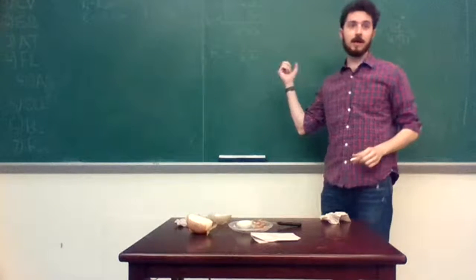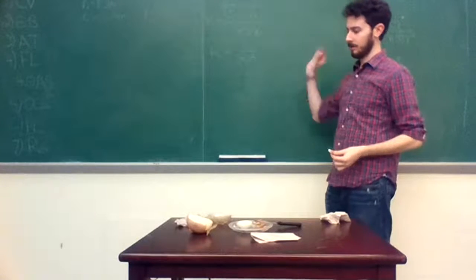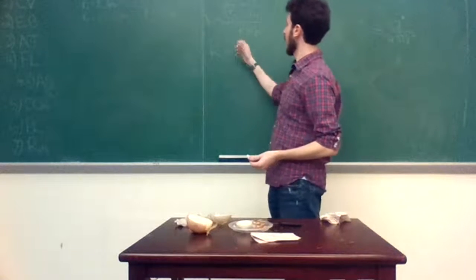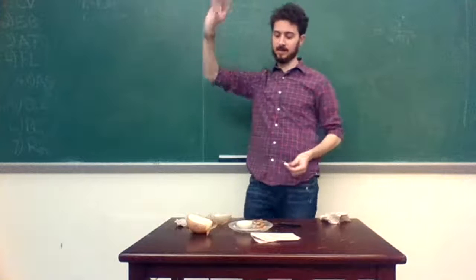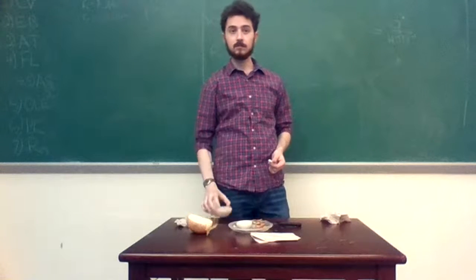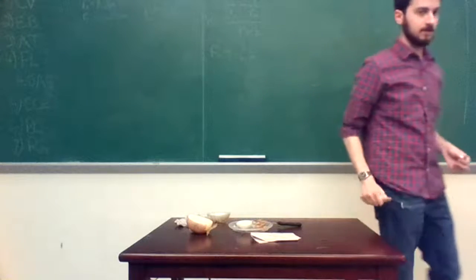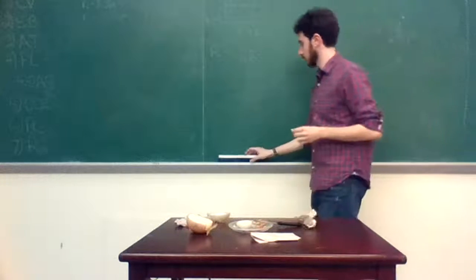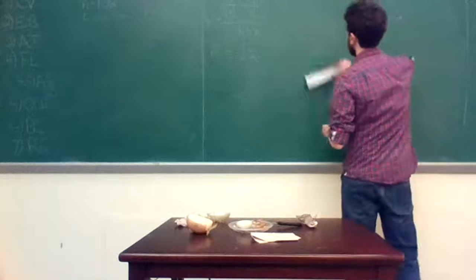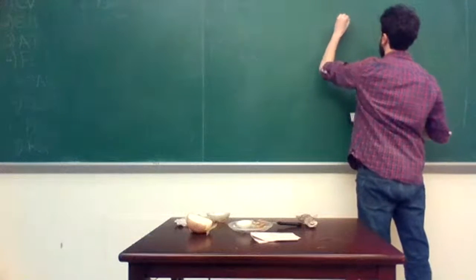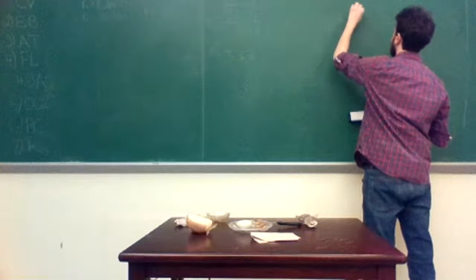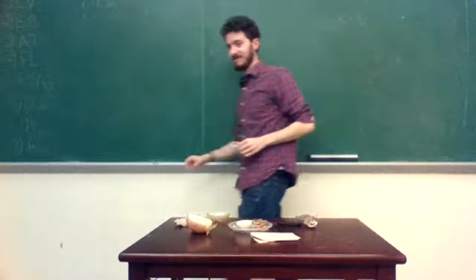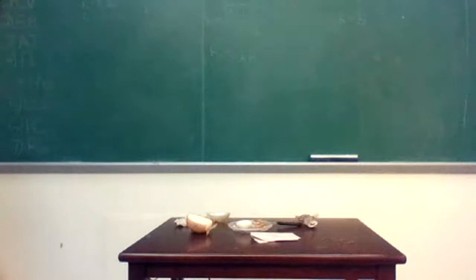Now you've got to compute your area, which is going to be 4 pi r squared. We're going to pretend it's a slab. And here L is really just t, right? Your thickness of that shell. Very, very thin layer of onion. Oh, and then sorry, what's k, Declan? He's reading a research paper. Yeah, I'm skimming a research paper. Just give me a value. Let's go with 0.5 watts. Have I omitted any data you need? Everything's geometric plus thermal conductivity. Yeah. Okay.